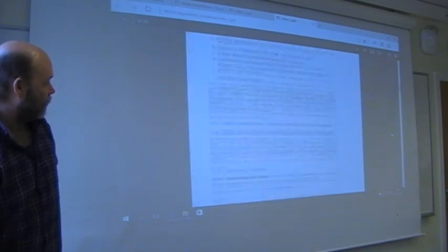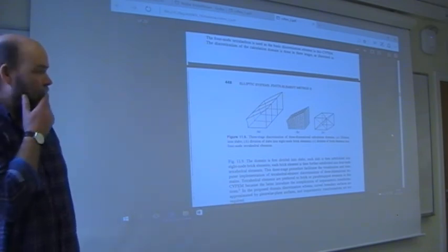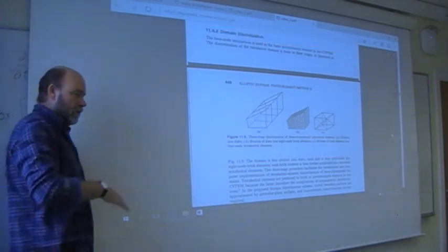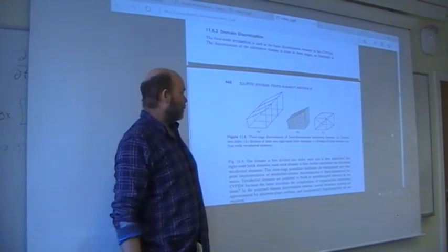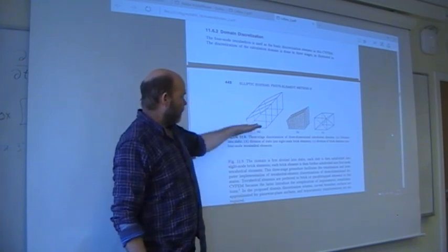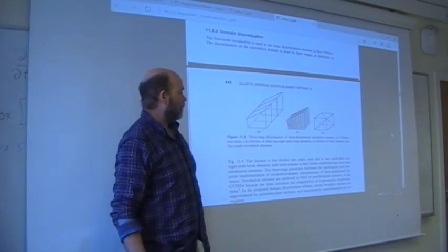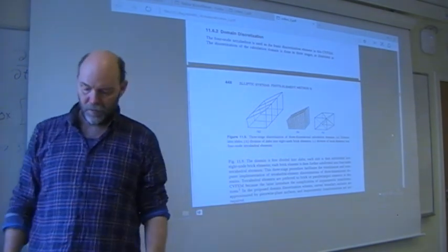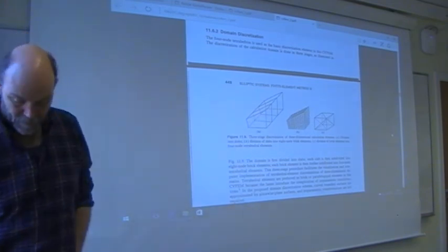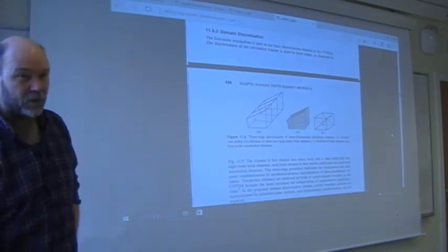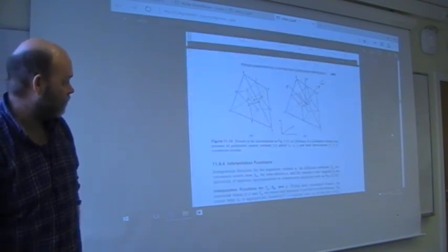Talk a little bit about jumping into 3 dimensions. And as I said, normally what you will try to do, if you have a nasty geometry, at least see if you have one direction where you just can use the same mesh. So you sort of extrude your complicated unstructured 2D mesh into 3D. Because jumping into pyramids and other shaped elements, that's massive, slow, expensive. So if possible, try to avoid it.